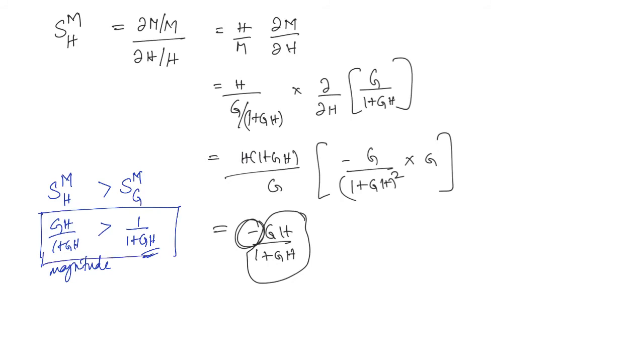It means that the system is more sensitive to variations in the feedback path. That is why we often see to it that whatever components we are using in the feedback path transfer function do not have much variation, so that if there are no variations, then there will not be any effect.